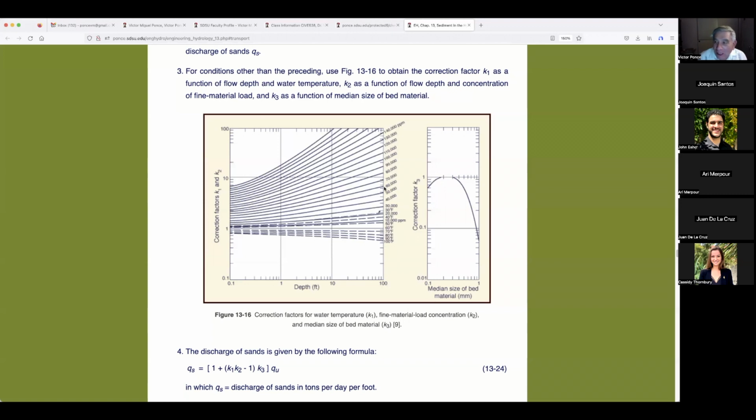But the fact of the matter is that the heavy wash loads are part of what we call debris flows and high concentration, high sediment concentration loads. Anything above 50,000 is already considered our high sediment transport. 50,000 is over here. So we can get all the way to 140, 120,000 numbers, extreme numbers of 200,000 have been seen in this sense. Although Colby never got to 200,000, presumably because he never felt it was necessary. But 140, roughly very close to 200,000. So he makes these corrections against the K2. And for the K3, he deviates from the 0.2 to 0.3 over here. Anything less than 0.2 will have a correction, K3 less, likewise greater than 0.3, also correction. If you get to 1, the correction is extremely high.